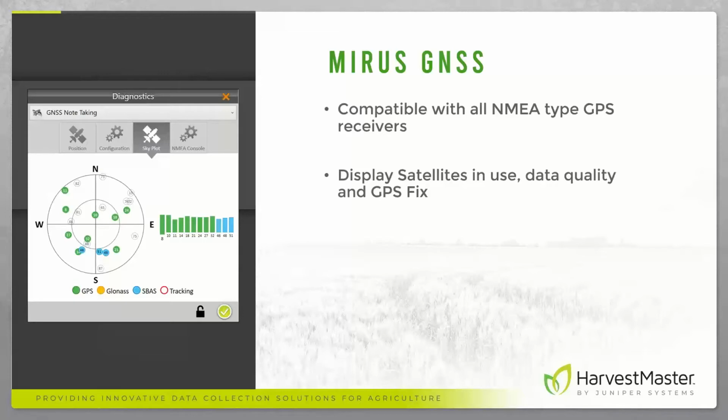The quality or the fix that we're at can be looked at here. The NMEA console will come up showing what NMEA strings are being sent out. You can configure the position. So this is all diagnostics for the GNSS, and you can know a lot of the things for getting it set up and just where you're at and what data you're getting in from your receiver.